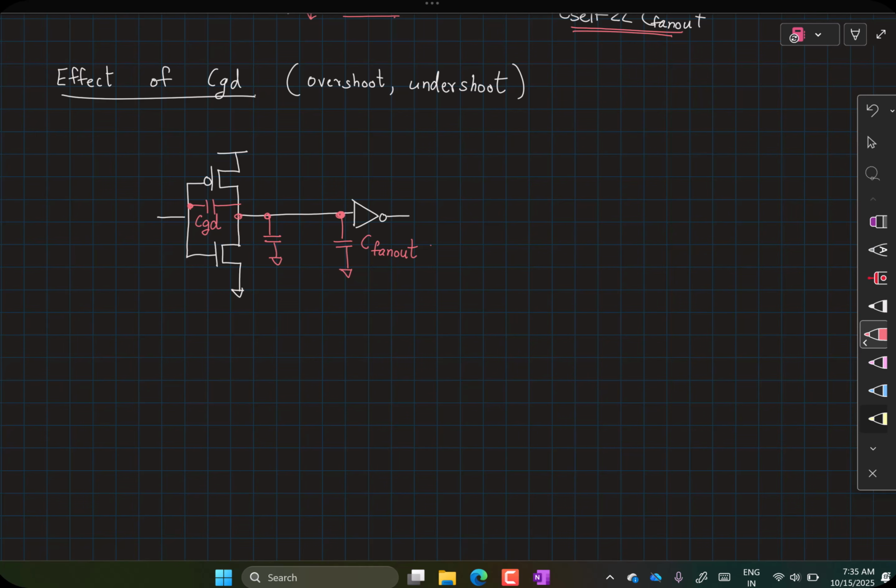Now, if you had a rising edge here, a signal that is going from 0 to VDD, you can see that there is this capacitance here where one terminal is suddenly increasing from 0 to VDD. Right? So based on all the RC network analysis that you have done, you would expect that at the instant at which this change is happening, this node also gets pulled up, right? Some sort of capacitive coupling. Now, this is absolutely correct. You will have a small increase in this node, and let me show you how that is going to look like.